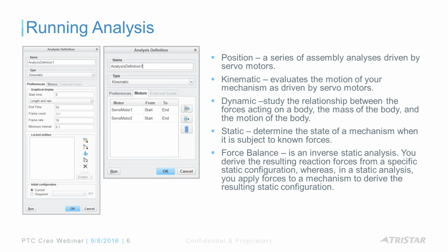You derive the result reaction forces from a specific static configuration. So in the static analysis, you apply the forces. On this one, actually, your result will be the forces. So think of one of those toolboxes that you put on the back of a truck, and you've got the cover for that one, and a piston holding it down, right? Maybe you want to find out how much force you need in order for that piston to actually fully disengage, and allow the cover to open fully. That's something that you can do with the force balance.